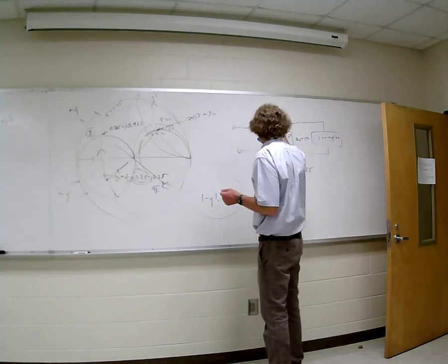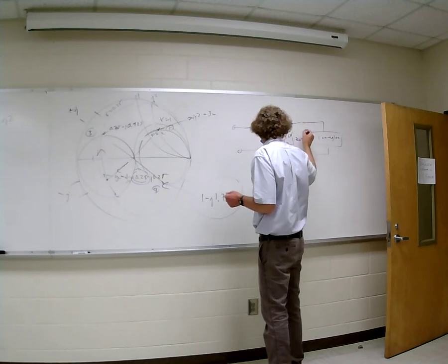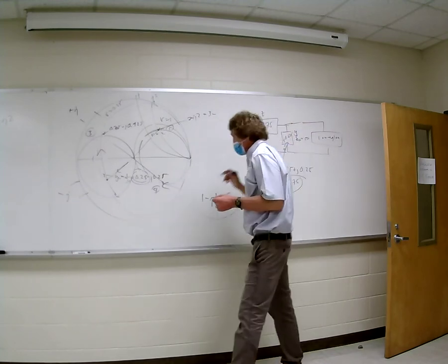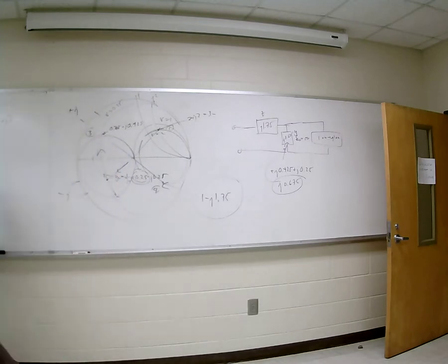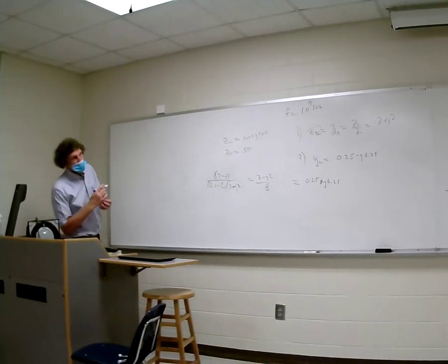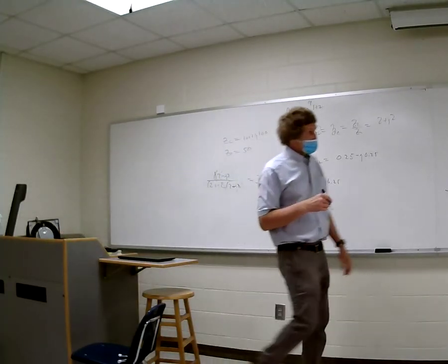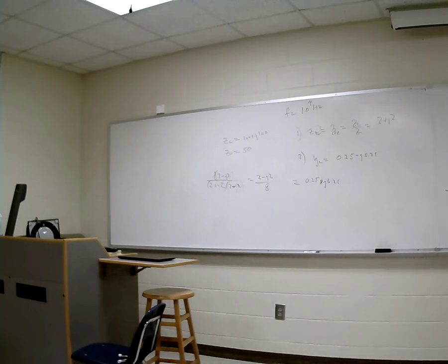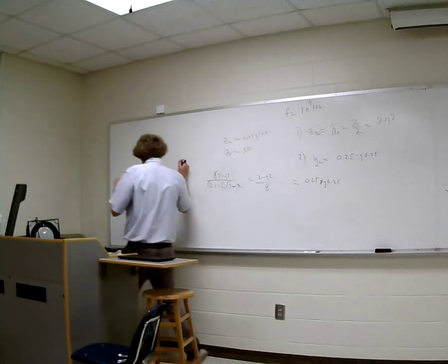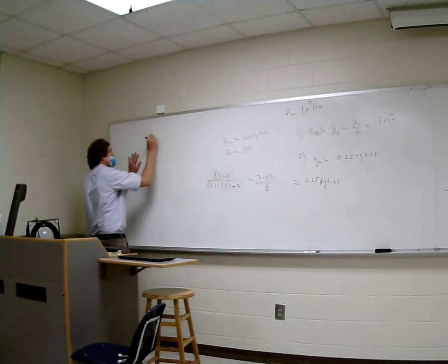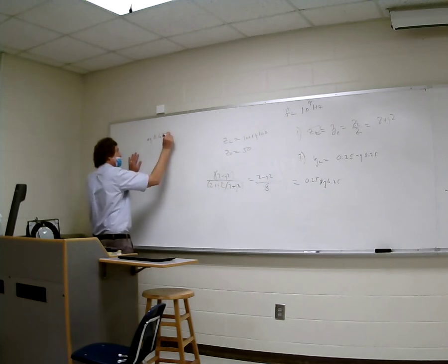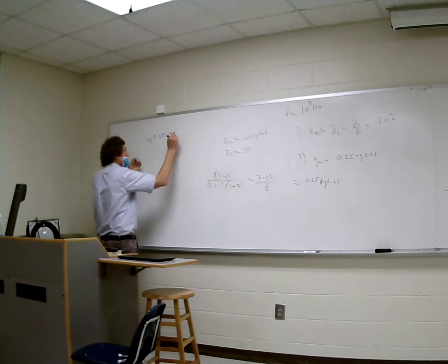Except for one thing, this is in the impedance domain, it's normalized, this is in the admittance domain. So now I have to get the actual values of the components, correct, class? Is everybody with me on this one? All right, now, how do we get the components? We'll start with the admittance. We have a value that we have to render of j 0.675, right? It's normalized. So I say I have plus j 0.675, and that's the normalized admittance of this element.